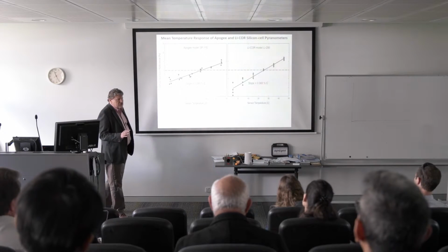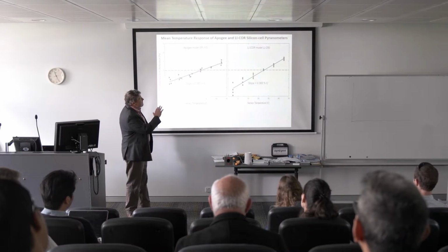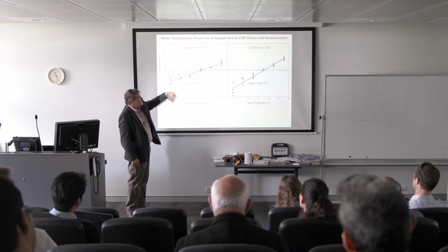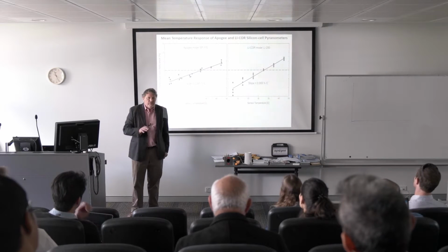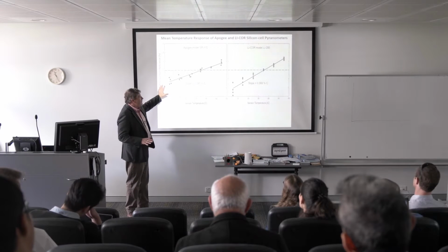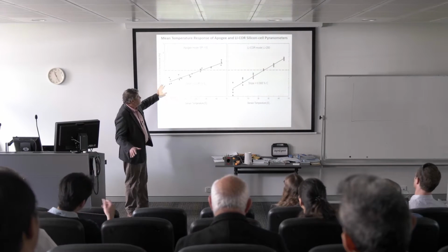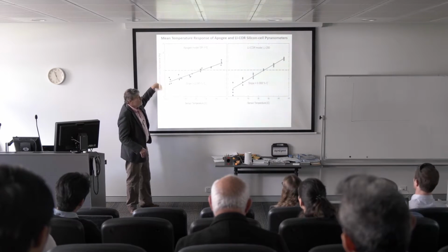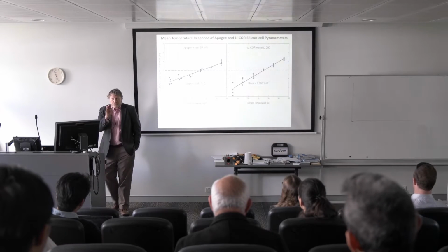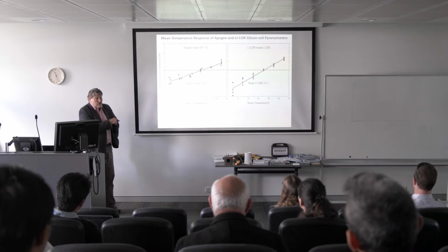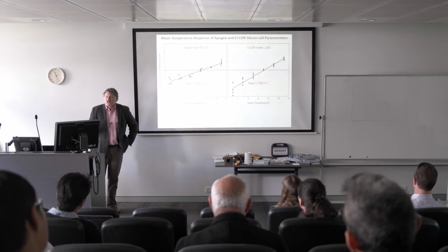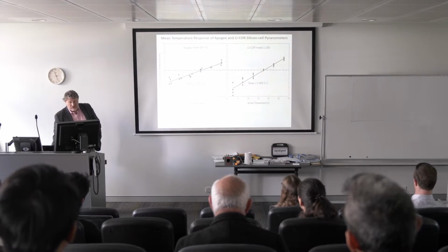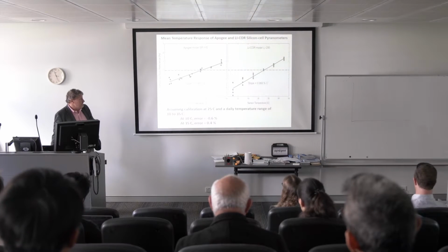Temperature affects radiation sensors. This is an example of comparative tests that we've done with LICOR silicon pyranometers and ours. There's a tiny temperature effect in here. Most research grade sensors, this is a small effect. Look at this, goes from -10 to +40, and the effect is only 1%. So again, for precision measurements, this is repeatable, so you can measure and correct for the temperature effect on the sensor. It depends on how accurate you need the solar radiation.